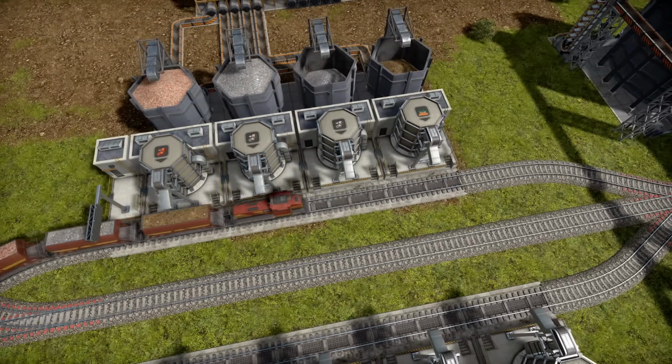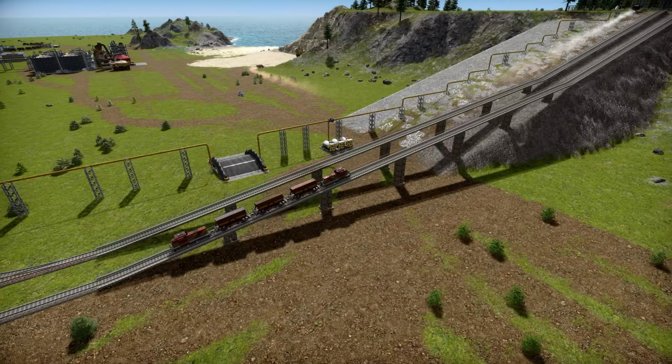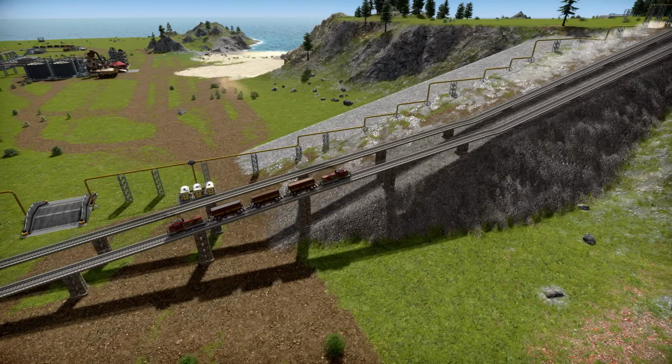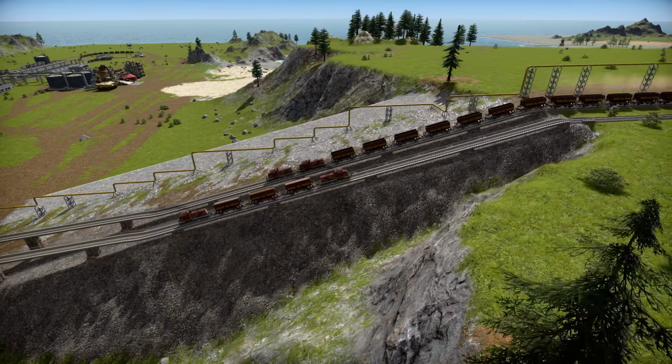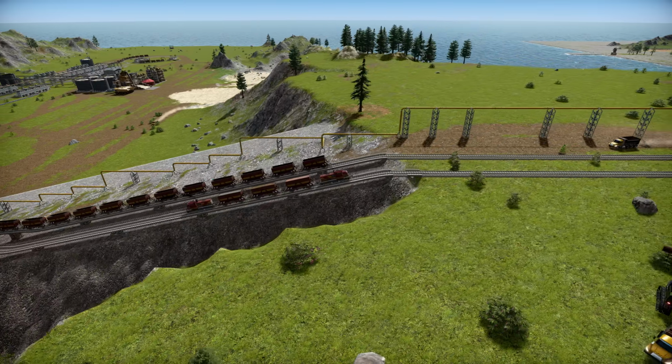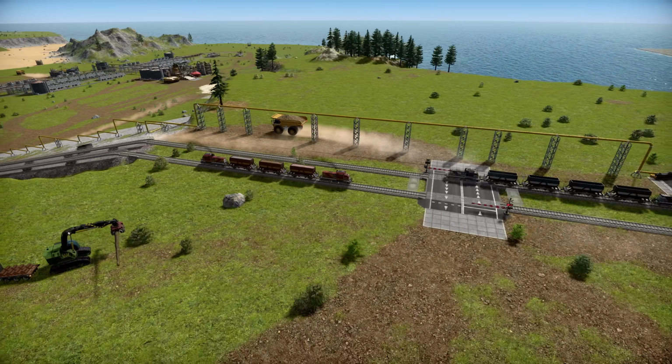Use line filters for broad stop level control and wagon filters for precise train level behavior. But try to avoid overlapping these two filter methods when possible. If line filters are sufficient for your needs, wagon filters are not required and vice versa. Decide what is best for your network.